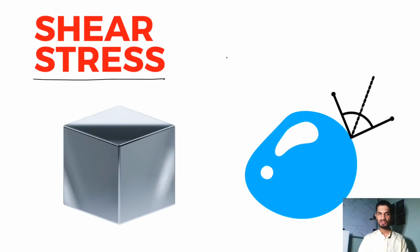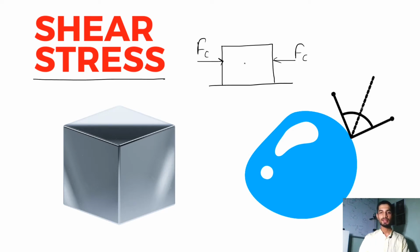Now what is this stress? Stress is the internal resisting force acting opposite to the force that we have applied on a body. Let's say this is the compression force I am applying to the body to shorten it, but there is some internal resisting force which comes into play in order to create some resistance against this compression force that I apply. So this internal resisting force will be known as compressive stress.